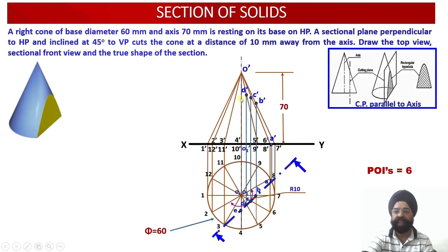So earlier we converted height into radius, but now since the radius is given, we have to look at this particular point from the 90-degree angle. So how that will be done, please see. I will keep the compass needle over here at the point O, the axis point, and I'll open my compass to OE, equal to OE, because I know the radius. Since I know the radius of this arc, I will project it so that I transfer it at a distance of 90 degrees over there. I want to look at this cone from the 90-degree orientation.